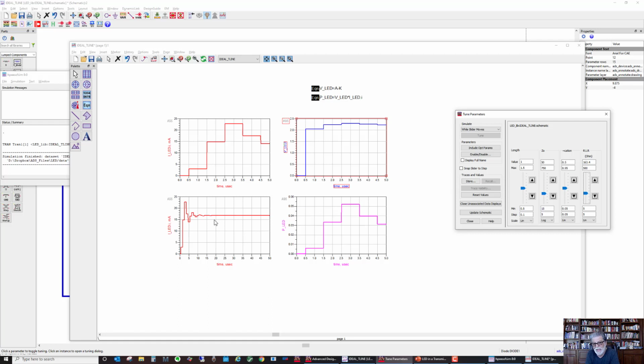Then it'll stabilize. But up until it gets stabilized, we'll see the LED light after the delay of the first cable. We'll see some really wacky responses based on the matching or mismatching of the system, and eventually settling out to the resistance that's defined by the resistor.